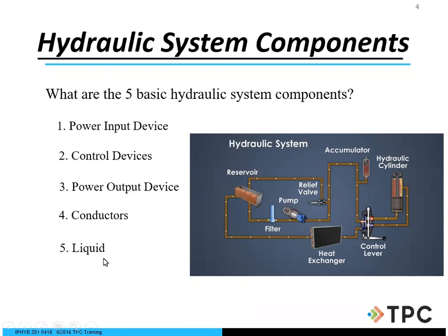Is the liquid going to stay cool or consistent throughout our hydraulic system as it travels through the piping or the conduit or the conductors? The fluid, as it travels, creates friction with whatever surface we're working with. It could be that rubber hose, or it could be that metal pipe. Either one is creating that friction. So the smaller the conductor, the more heat is going to be generated. So how much heat can we withstand before we put in a heat exchanger?